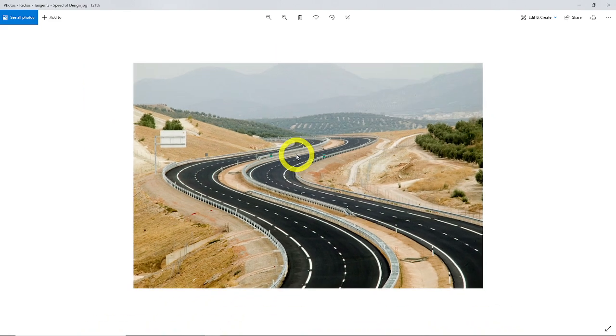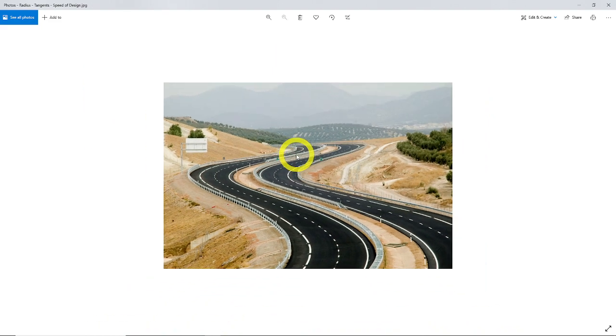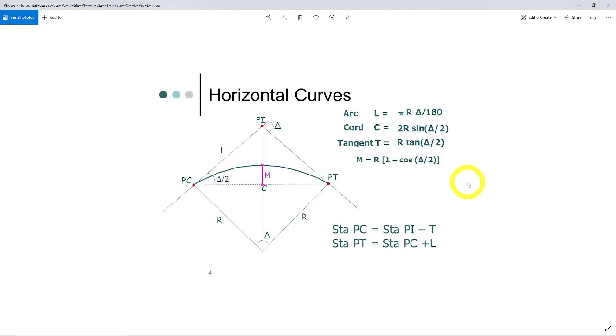as well as surveying. So if we go back a couple steps in this picture, here's a simple alignment curve. So it starts by entering this direction. It goes into what we call a PC, a point of curvature, which in this case, let's assume it's tangent, which it is in this depiction, goes to a radius into this curve or arc that has a radius, which is this distance, half the circle, in this case arc, half of this arc diameter.